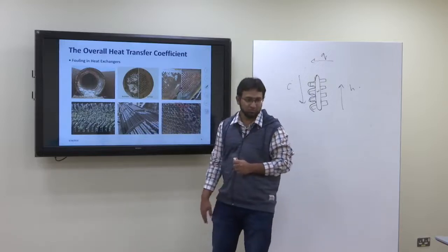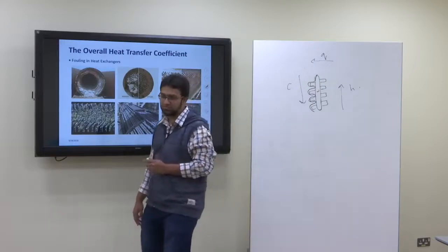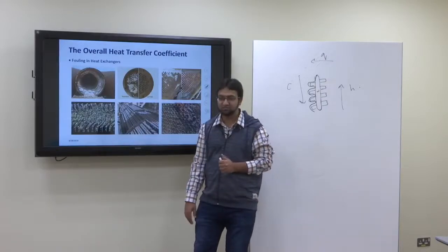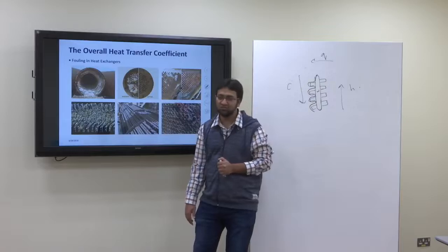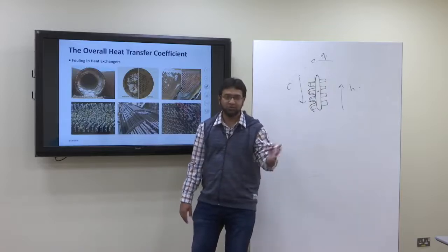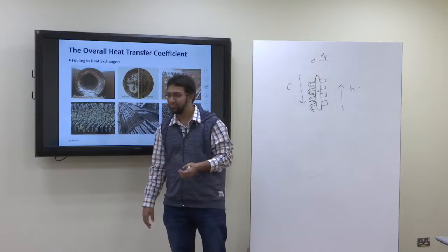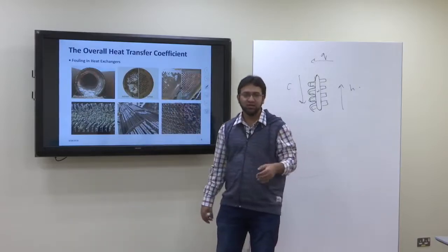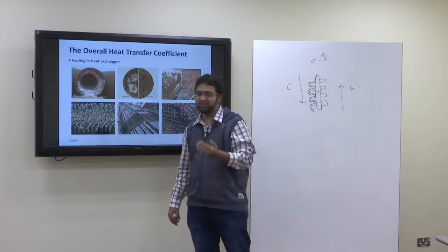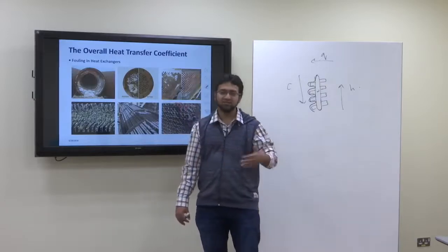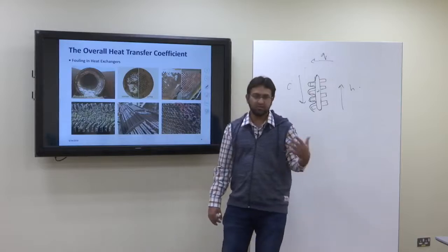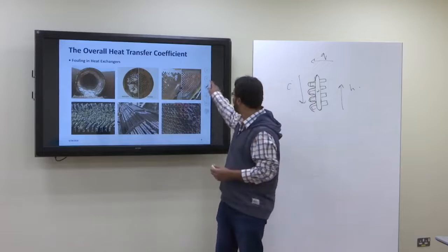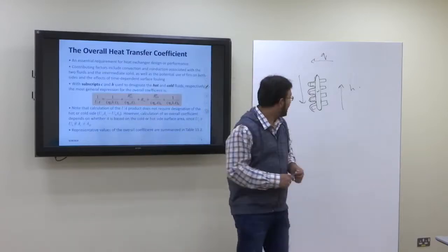So this fouling is a major concern, obviously, and for the designers of heat exchangers, they must take into consideration what kind of flow is going through it and how much fouling is expected. And once you design the heat exchanger, it's not possible to really do the cleaning inside. There are certain ways we can try, but obviously it's not really that viable.